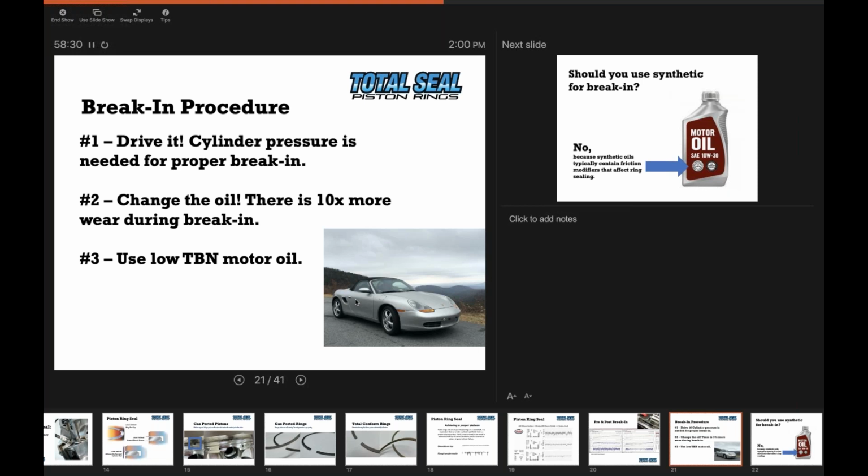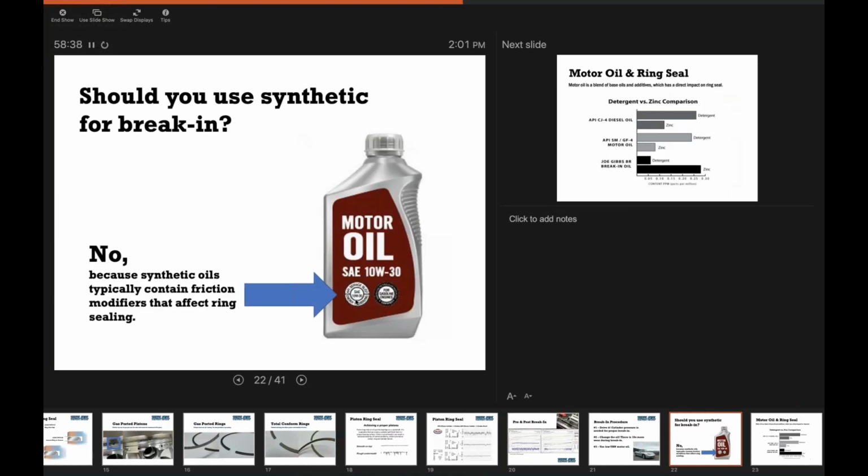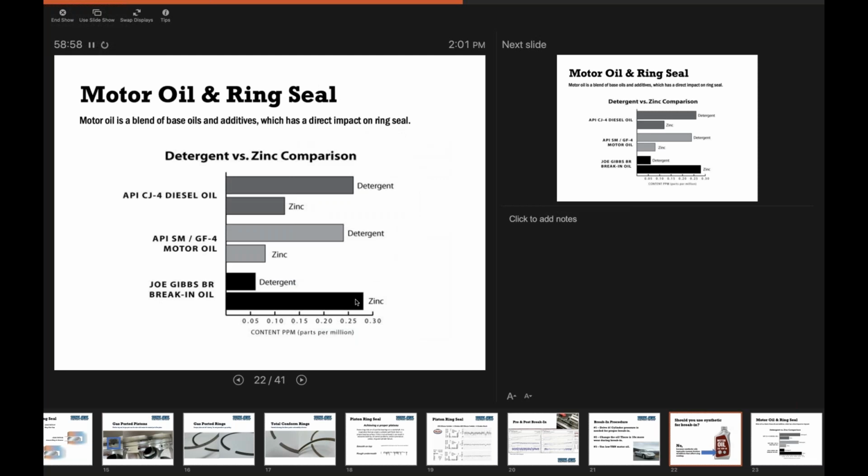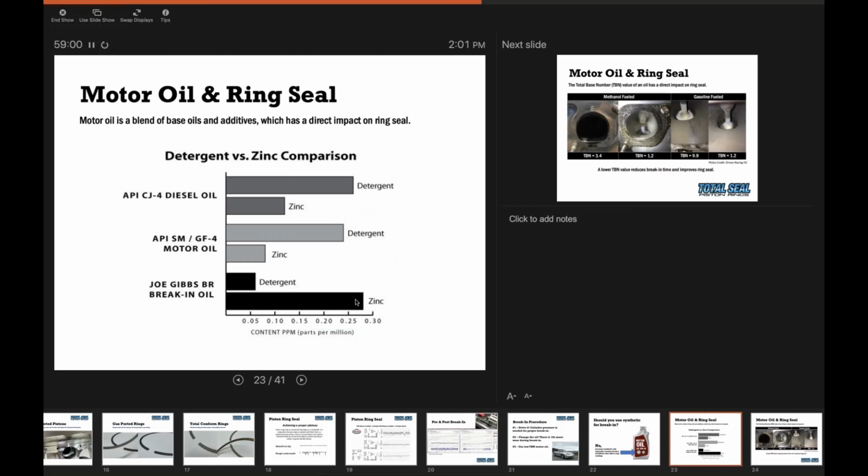We did a webinar back in January that talked specifically about that, that really gets into the details. I can kind of hit the highlights. One, should you use a synthetic oil for break-in? The simple answer is no, not because it's synthetic necessarily, but because typically those oils contain friction modifiers that are going to reduce friction, which is not what you want, and they typically have a higher TBN because they're designed to live a long time in the engine, and high TBN, high detergency works against ring seal.